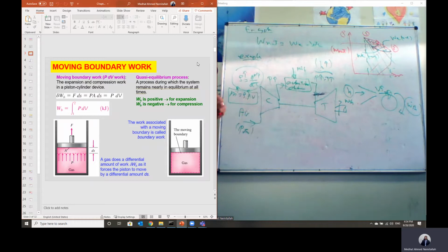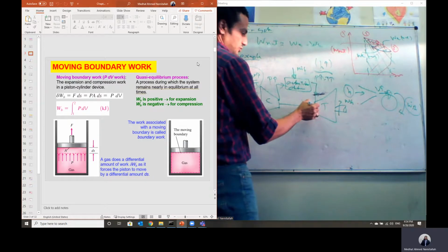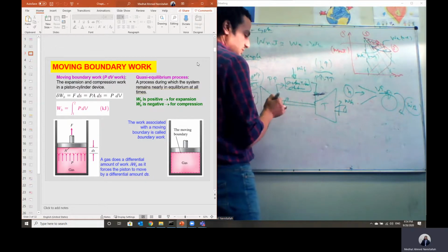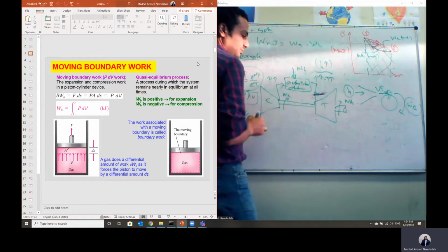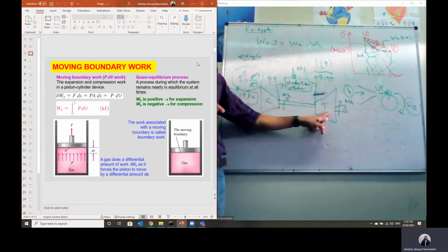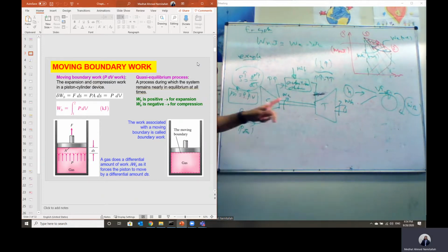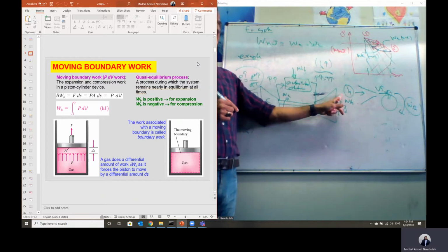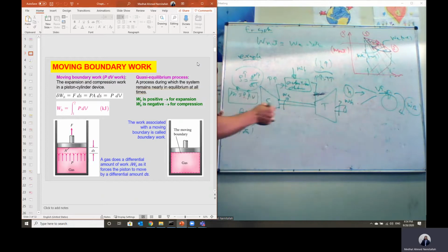To drive this compressor, its function is the reverse of the turbine. It takes the air at low pressure and raises the pressure. So it increases the flow energy of the air. But in comparison to the turbine, it has to consume shaft power. So we have work input to the compressor in this case. That's why we connect the compressor to the turbine on the same shaft. So part of the shaft power output of this turbine will be used to run this compressor.